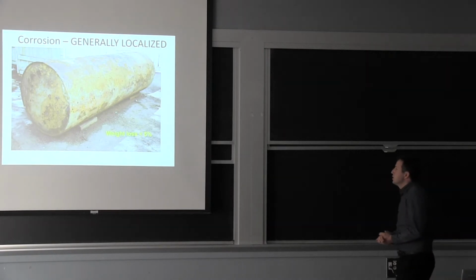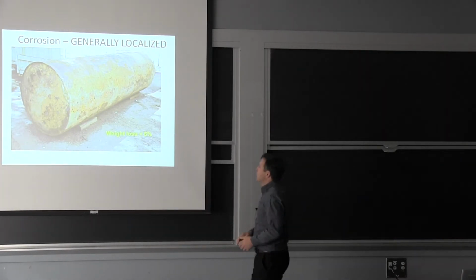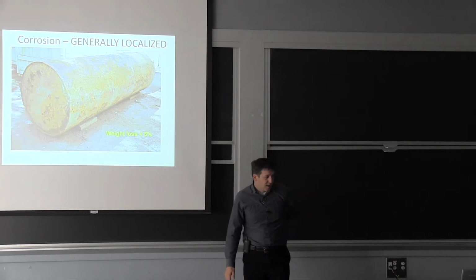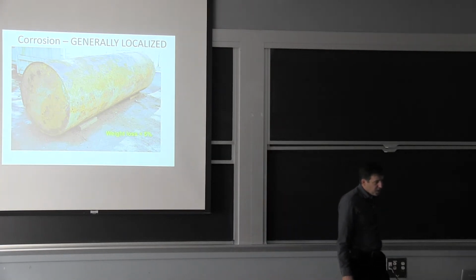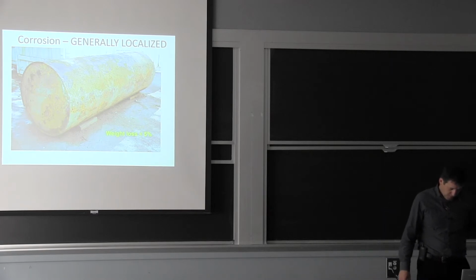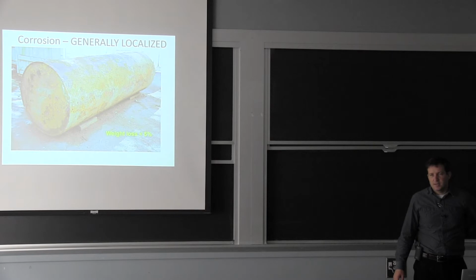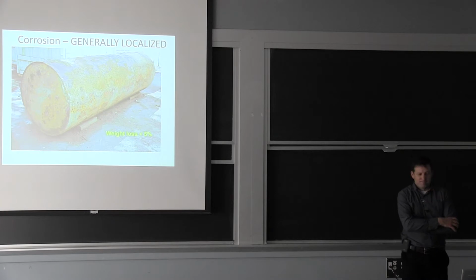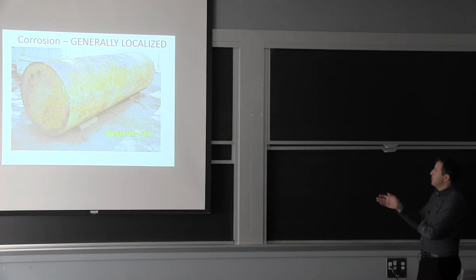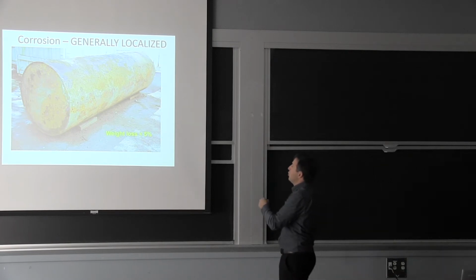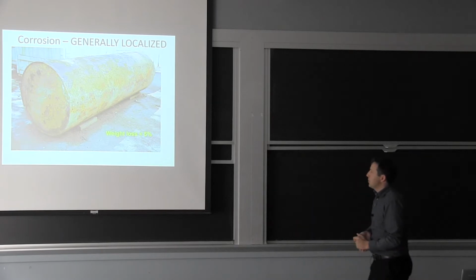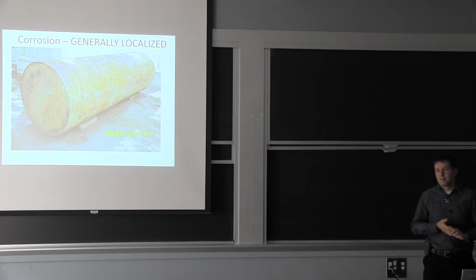If you remember, I mentioned that the corrosion rate is going to vary. So here you have an underground storage tank that was not protected. It was a domestic installation, even though the tank is way bigger than what you normally have in your yard. What happened here, and I mentioned the water table to you guys, is the bottom of the tank, which you see on the right-hand side, has holes through it. And the top of it was pretty much the original wall thickness. So it's just an example. When I was saying underground, you can have a lot of variation. Well, that's the best example of that.